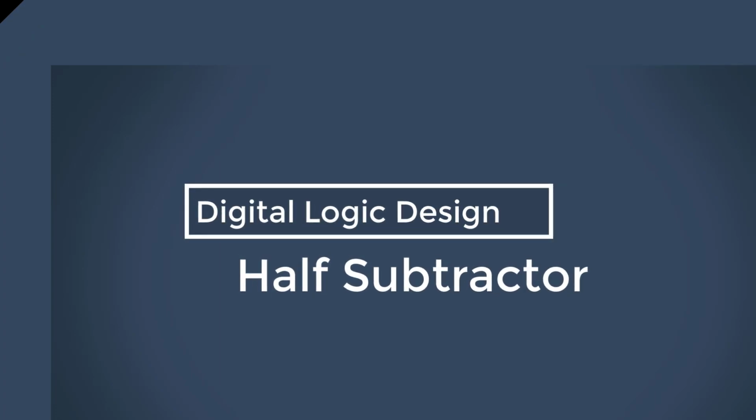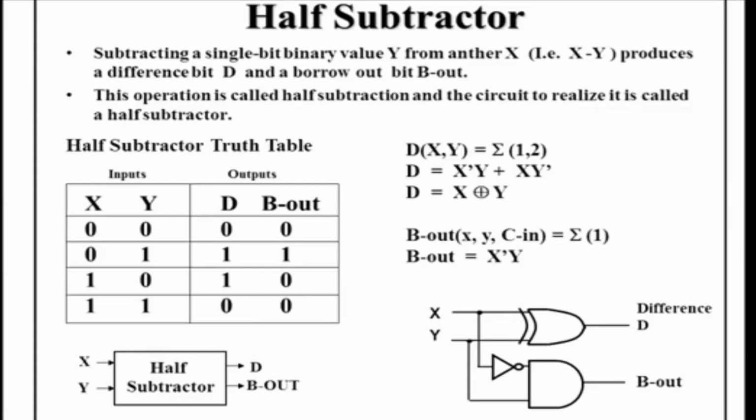Now we'll move on to half subtractor, which is similar to a half adder, but the only difference is that it performs subtraction and produces the difference and the borrow out. So subtracting a single bit binary value y from another value x is done with the help of a half subtractor to produce a difference bit d and a borrow bit b out. This operation is called half subtraction, and the circuit which is used to realize it is called a half subtractor. Let's look into the truth table of a half subtractor.